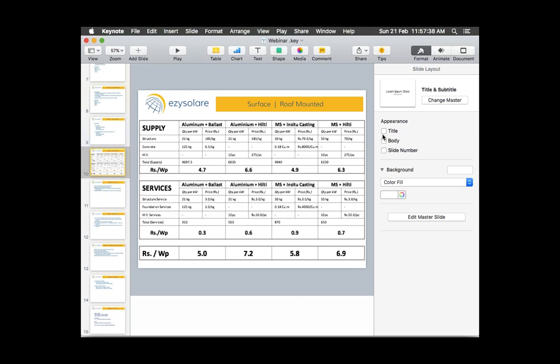Somebody has asked a question on double axis trackers. I am aware, Sathish, that you guys did a double axis 50 kilowatt tracker somewhere. If you can share your experience on the double axis tracker. With the double axis tracker, both axes will be rotating, and the tonnage per megawatt will be much higher as compared to the single axis. So if you can give us some range of what the tonnage will be, and what the difficulties are with the dual axis tracker.